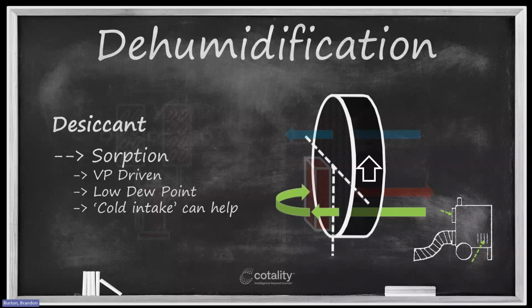First and foremost, a desiccant dehumidifier is generally not the right type of dehumidification to use, especially in the early phases of drying, when you're dealing with a lot of highly porous materials, a high degree of saturation, and rapid airflow immediately over damp surfaces with high evaporation rates. In other words, it's not a very effective system for a class 2 or class 3 water damage, with these higher evaporation rates. The reason is that the rotor can only hold on to so much moisture at a time. You're going to hit the upper-end max performance that the desiccant has, and everything above that is just going to pass right through the rotor.